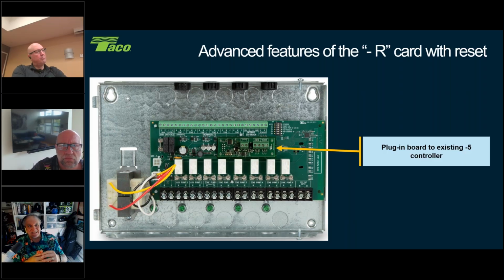If you know the delta P that the circulator is creating, if you know what that pressure differential is, you may be able to convert that to feet of head and figure out the flow rate based on your pump performance curve. The app doesn't do either of those for you. That's correct. It's got to be done manually. All we're doing is sending the signal out to a pump and telling it to run. You could do it, but we don't have that built into the app.